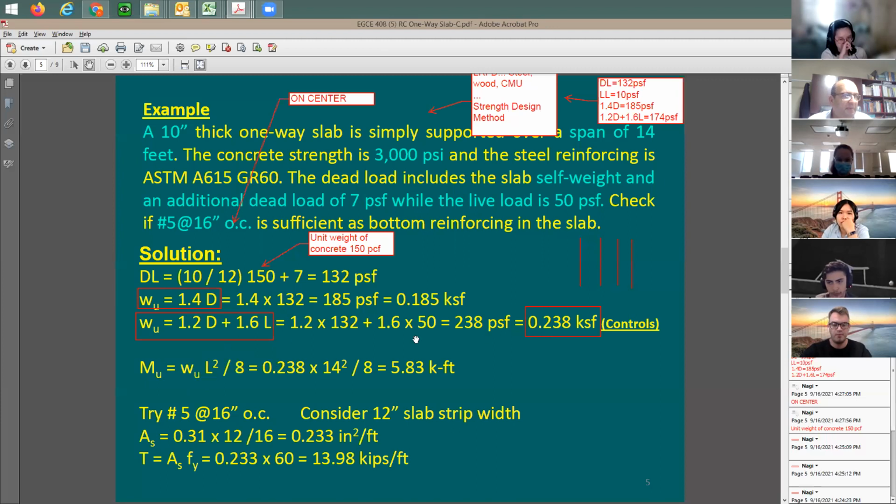Does that make sense? Because when you have here kip per square foot, you'd like first to put it as kip per linear foot. Let me write this down. The load that you'd like to use here for beams is going to be the load W. It has to be in kip per foot, correct? It is not really kip per square foot. So what happened? Simply that I said, well, the strip width here is going to be exactly 1 foot.